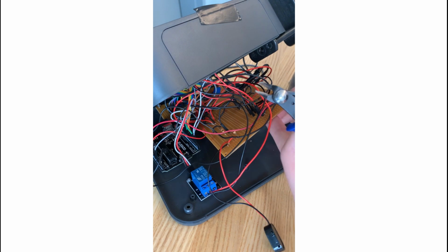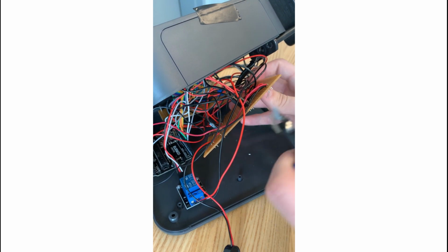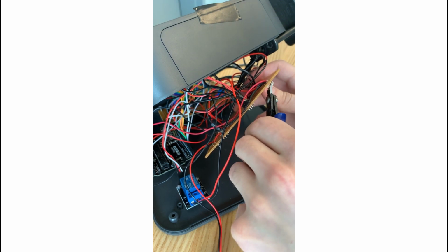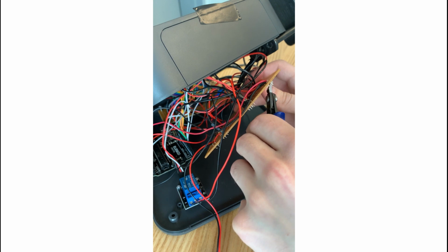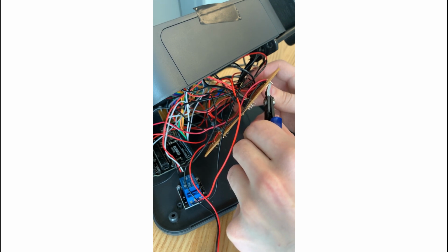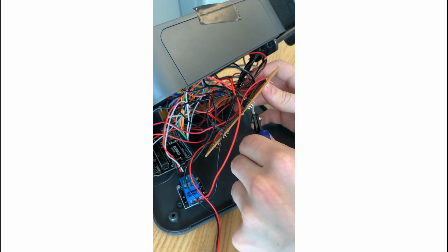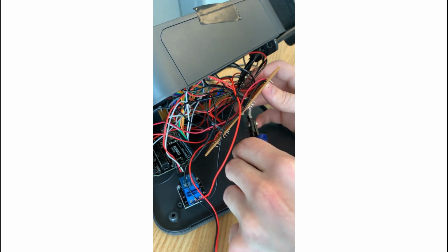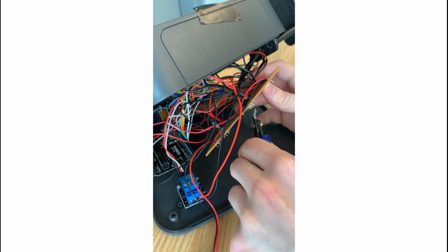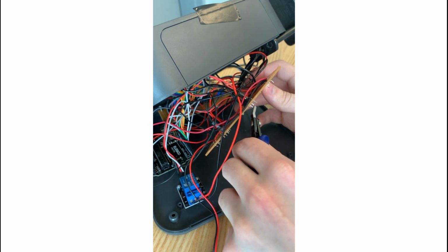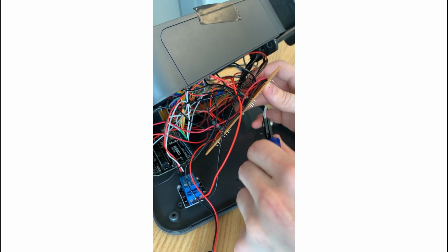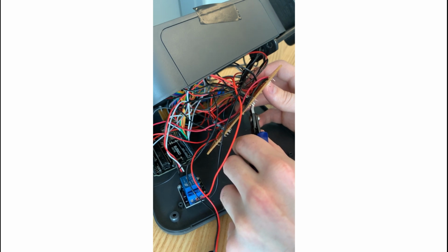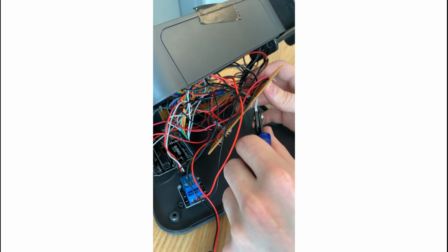Before enclosing the box, I went through some final testing to ensure my circuit was still intact, and I cleaned up the soldering ends on my board, as shown here, to avoid any connections falling out or shorting when fixing my components inside of my product housing. My soldering boards and Arduino were either secured with hardware or double-sided Velcro inside the box, such that nothing slides around as the housing is moved. All sensors protruding through the exterior of the box were also fixed in place.